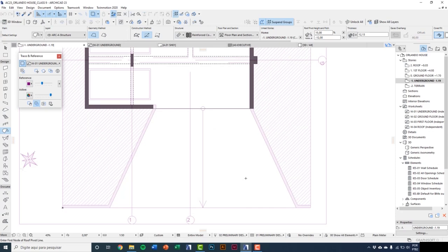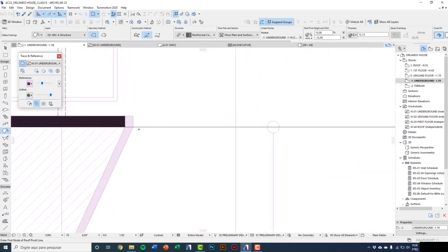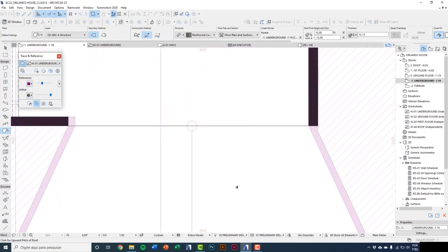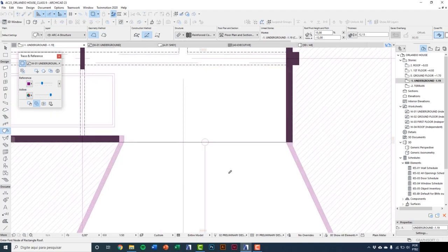Okay. To model a roof element, the first thing to do is a line that is a base reference. It will be the bottom edge of my ramp. I draw the line. An eye appears, and I need to click in one of the line sides to indicate roof ascendancy. I click below the line, a pencil appears, and now I can draw the geometry. I choose polygonal geometry and draw the ramp.